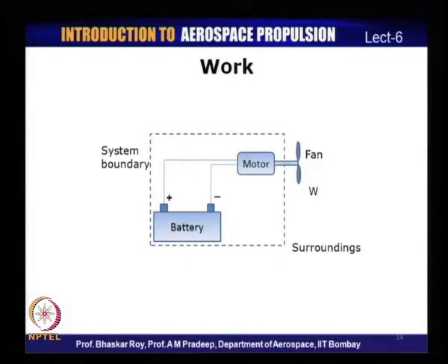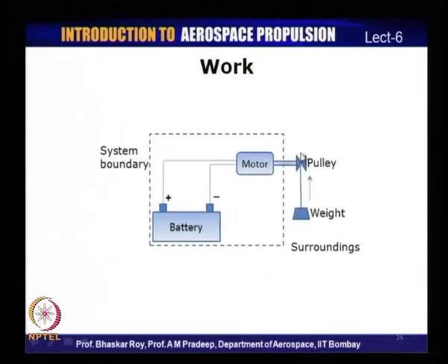Therefore, this example which has a system driving a fan definitely does work on the surroundings, because we can always replace this fan with a pulley and therefore raise a weight against gravity, and therefore, the system does work on the surroundings, as per the thermodynamic definition of work.